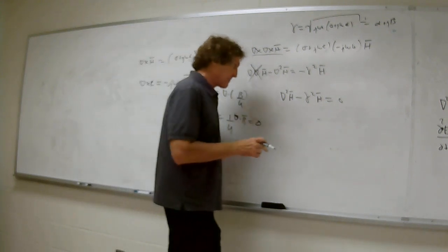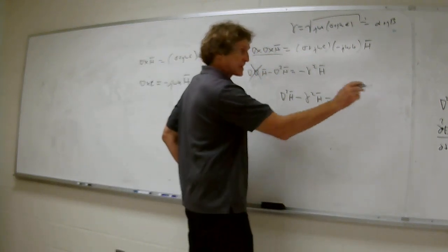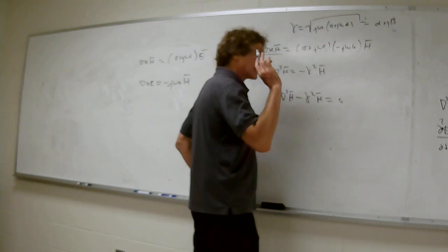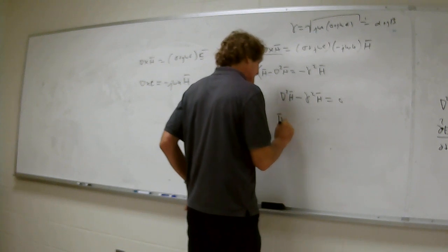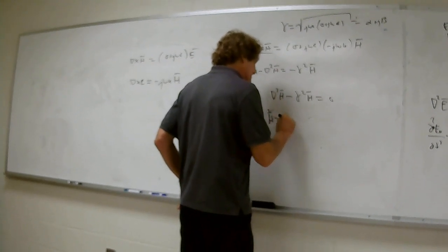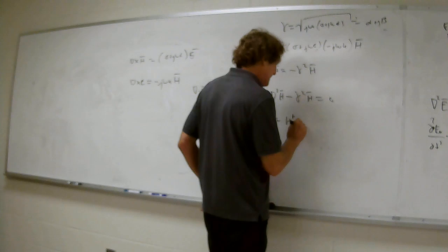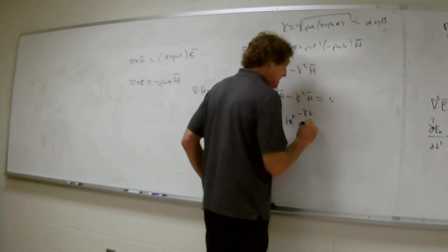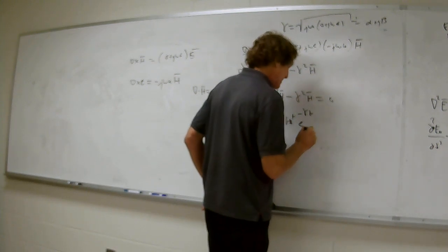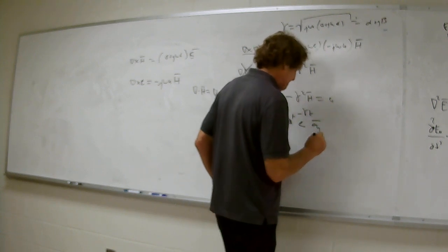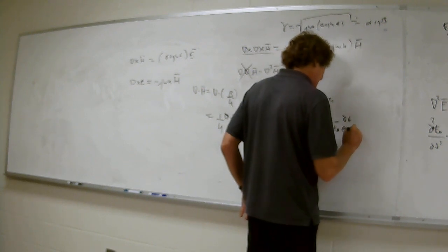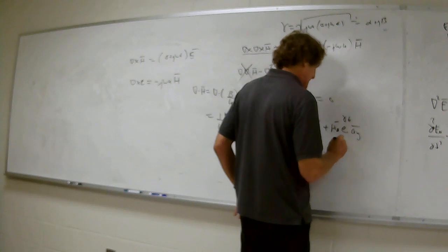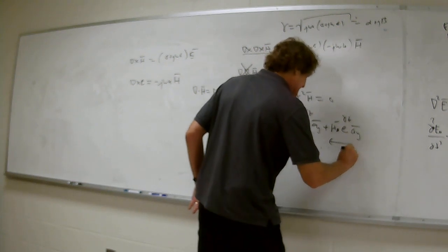That equation will have, again, 2 components, just like that one does. If we assume it's propagating in the z direction, plus or minus z, you're going to get an H field from this. It'll be equal to some H0 positive, and it'll be e to the minus gamma z in the a_y direction, plus H0 minus e to the plus gamma z in the a_y direction. And this is a wave traveling in the minus z direction.